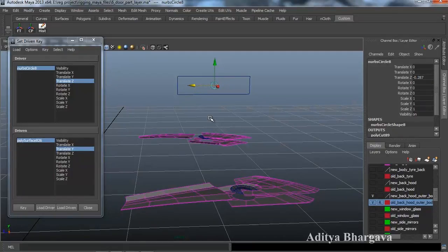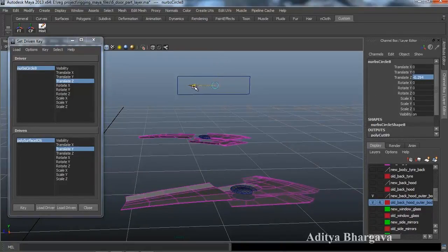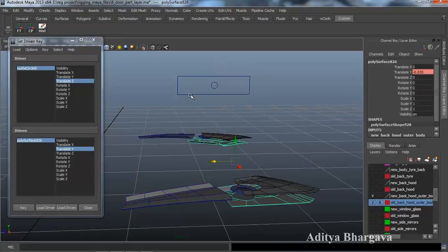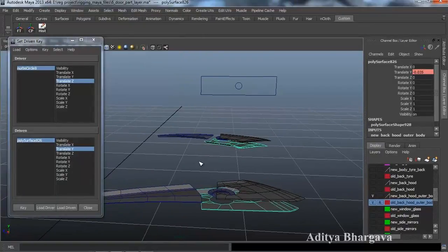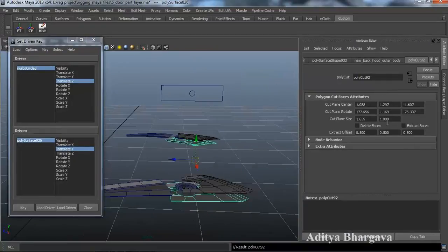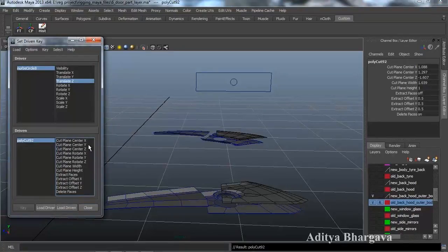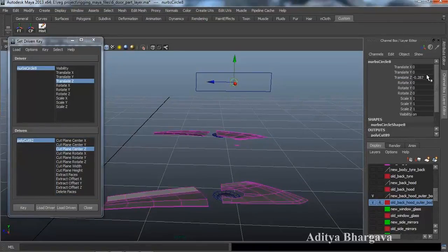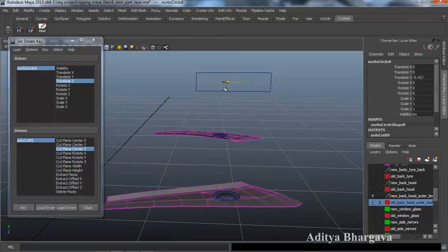take the controller backwards over here till this much part, and we'll first of all copy the final position of the controller, that is this one, Control C, we'll take it backwards till this much place, and we'll make this part go off the visibility here. For that we'll go to edit mesh and cut faces tool, and we'll add a cut face tool over here, press W, press Ctrl A, delete faces, we'll select the part, Ctrl A, we'll make it as a driven object, then select the Z axis, we'll make the part invisible at first, we'll set a key, then we'll put the final position of the controller, we'll press Ctrl V for that, we'll press enter, and then at this position we'll make the part come into visibility, and we'll add key. So this is what is happening right now.